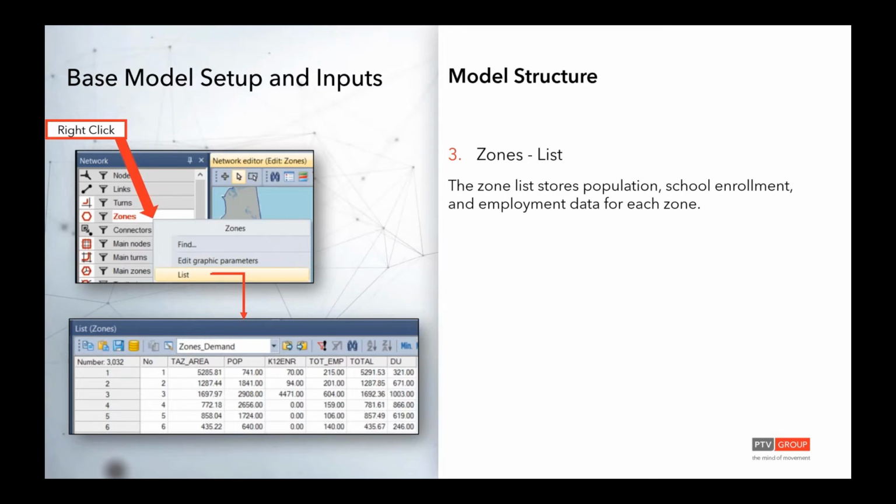In our particular model that we're looking at, there's going to be a lot of different subcategories. Now, I know that we had a question just before the break, asking about, do we need to keep zone numbers the same from one scenario to the next? And the answer is yes. If you want to compare those zones together, then they need to have the same ID, because Visum uses this node number attribute as the comparison attribute to identify which zones to compare.